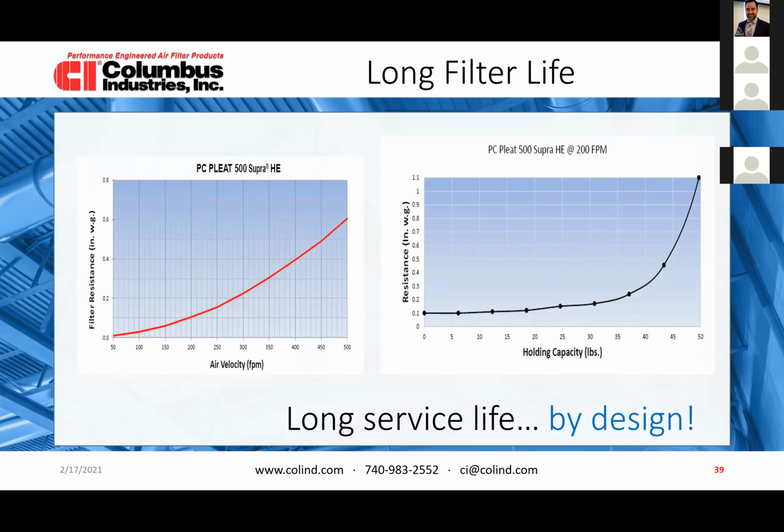Why does this filter last so long, and why does it capture so much paint without gaining pressure? It's by design. It's in the design of the way the layers are put together, but also the way the filter pleats are put together, so that the resistance to airflow stays flat as it loads with the pounds of paint. And then at a certain point, it goes up.